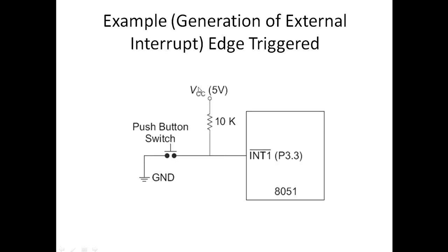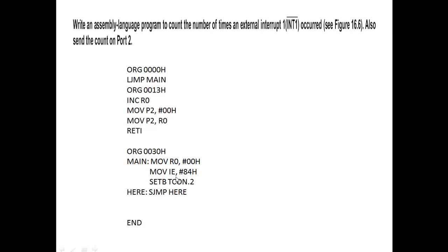Okay, remember that. So what we are doing is saving 00 in the R0 register. It's hexadecimal data, so all bits of R0 will be 000000 only. Now we initialize our IE, or enable our interrupt enable register, as per our requirement.